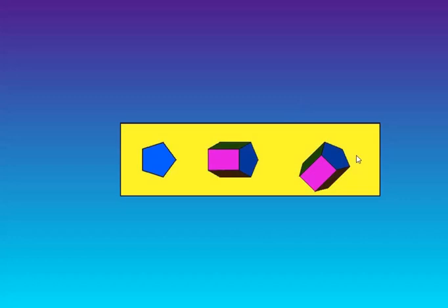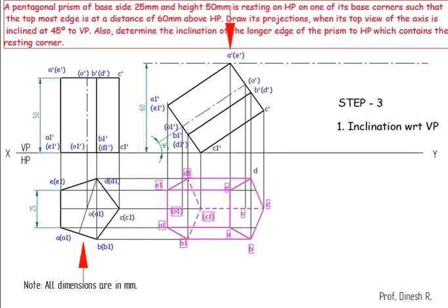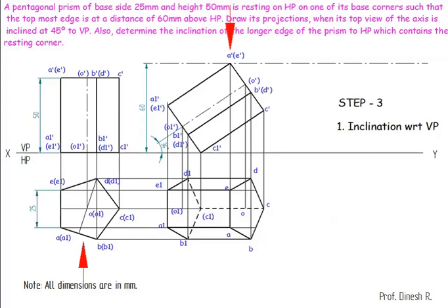This top view has been inclined, which is almost like in most of the problems where the axis appears to be inclined. So I will take this, and I'm going to draw a 45 degrees line. As soon as you get it, you are going to be drawing the angle which is 45 degrees.